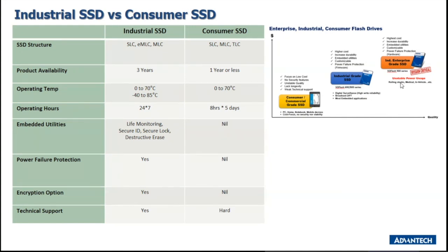TLC is also not meant for embedded applications due to the limited write cycle. Longevity is also very important for our long-term project design. A particular consumer SSD model won't supply you for long, and you may need to go through a very frequent requalification process.